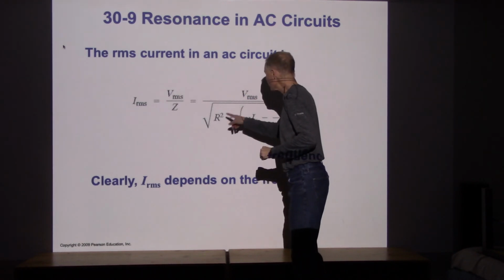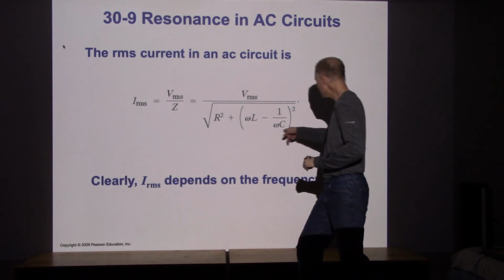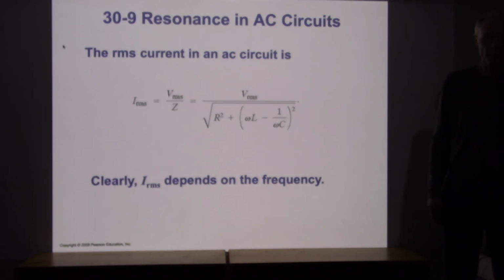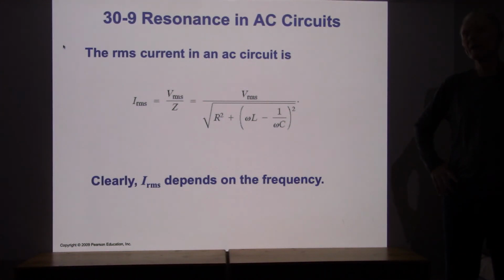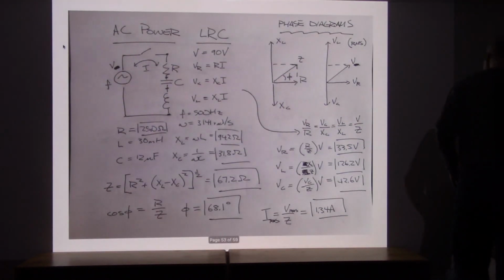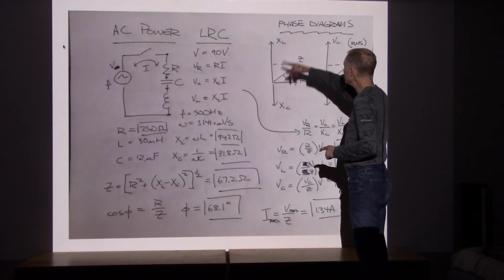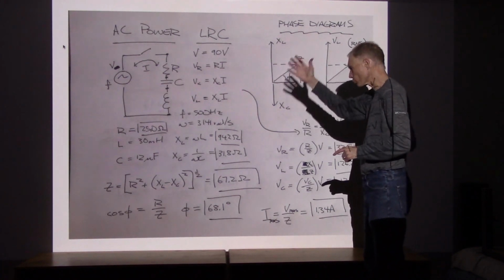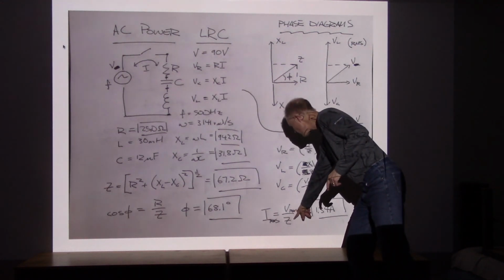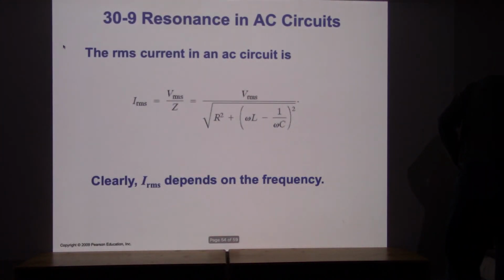In a series circuit of a resistor, inductor, and capacitor, the overall impedance is given by that stuff in the denominator. And it can be easily determined, I'm going to claim, using an impedance diagram that we looked at in the previous example. So I'm going to say, use these, really handy. You can use a diagram like this, run the numbers, and then put in the final Z, and figure out how much current we're going to have in that circuit.